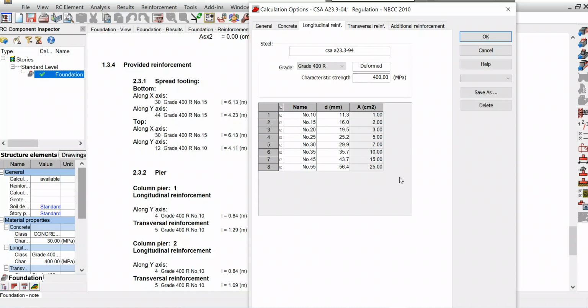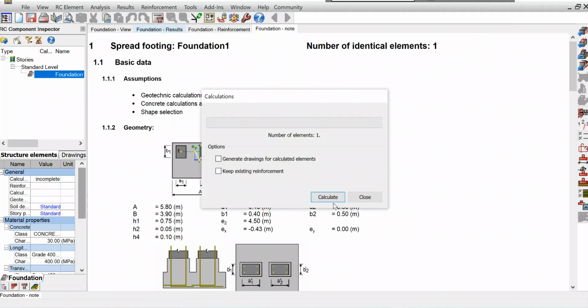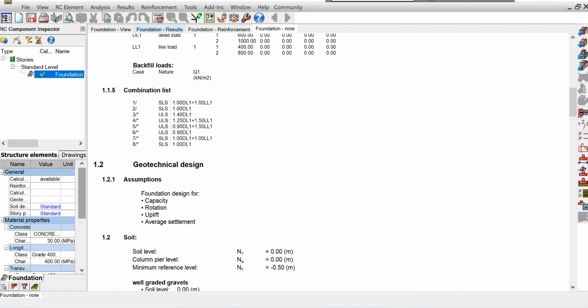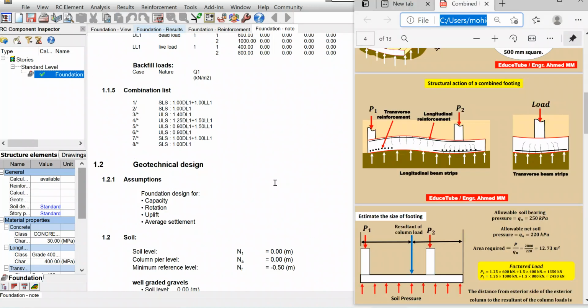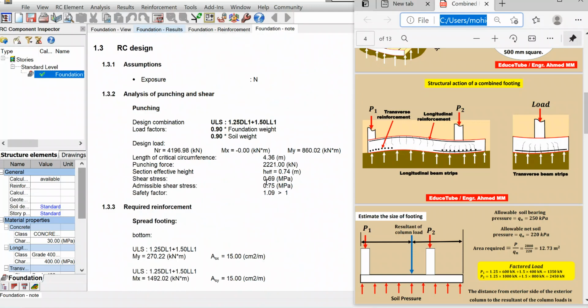And longitudinal reinforcement, actually I did not take this. I don't know how it came again. These two I already removed. So you have to be careful choosing this, otherwise it will select. So put this OK and go for analysis again. Do calculations and look at the result again, what you are finding. So go for RC design again.